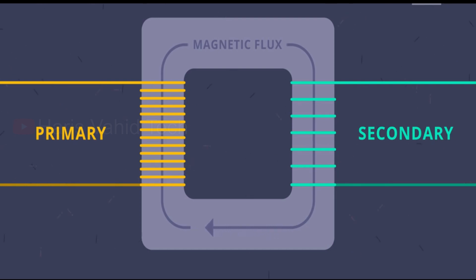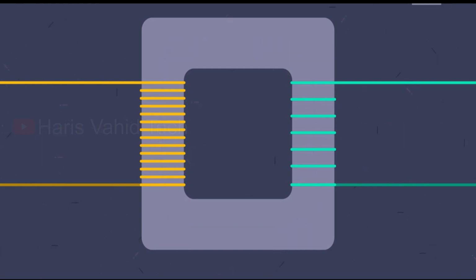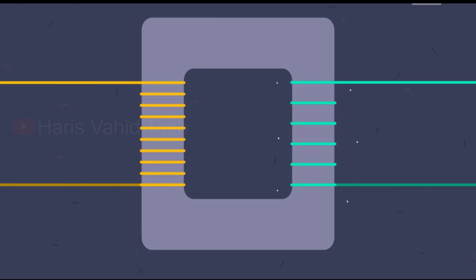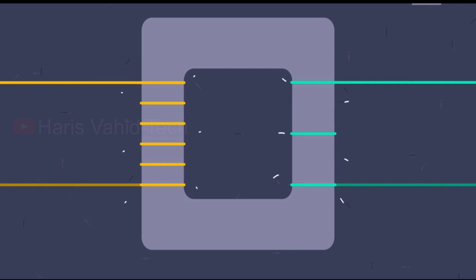The audio transformer works at frequencies between 20 Hz and 20 kHz, so the operation of an audio transformer has a much wider frequency range. As discussed above, the audio frequency transformer uses an impedance balancing technique. It is very useful for balancing amplifiers and loads that use different input or output impedances for maximum power transfer applications. In modern days, speaker impedance ranges from 4 to 16 ohms.